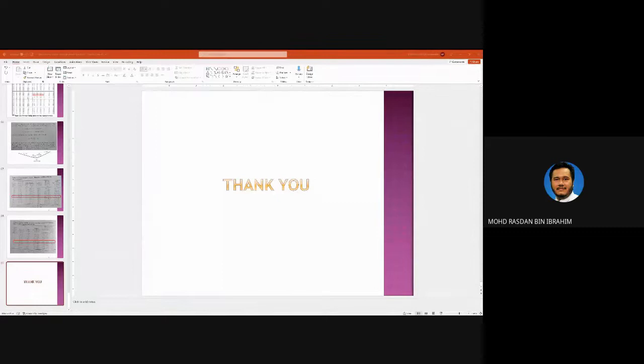But when we are dealing with reality in Malaysia and anywhere in the world, the constraints at site can be very significant. So this calls for other measures that we can use to aid our design. We can use, for example, rubber strips so that the vehicle will slow down. We have extra signboards, blinkers or anything to make sure that the vehicle slows down, or you can also put in mirrors.